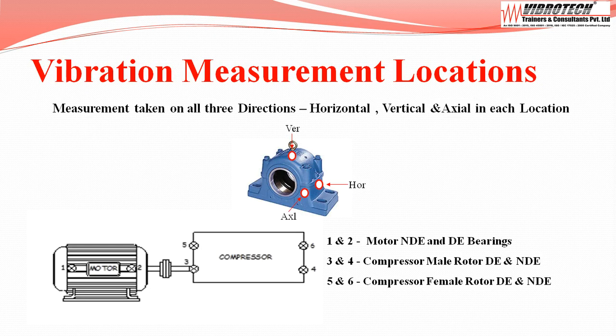Vibration measurements are taken in all three directions: horizontal, vertical, axial. The measurement locations are motor NDE bearing, motor DE bearing, compressor male rotor DE bearing, compressor male rotor NDE bearing, compressor female rotor DE bearing, and compressor female rotor NDE bearing.